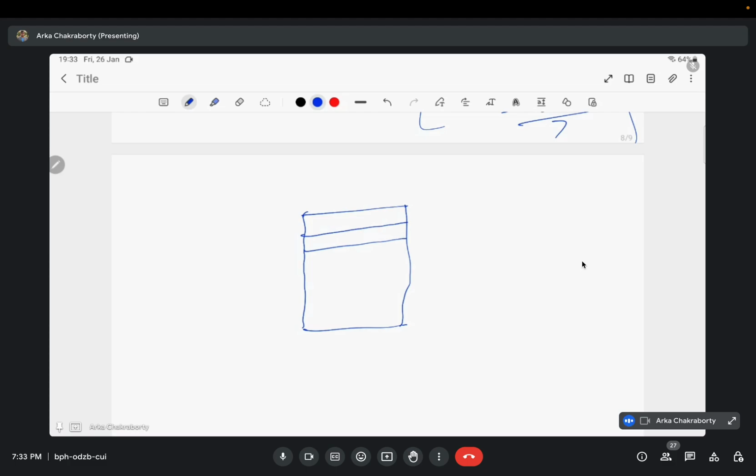Say it is a MOS capacitor. The upper layer is metal, the middle layer is oxide, and the bottom layer is semiconductor. So, metal oxide semiconductor. Say it is p-type silicon. This is called the gate terminal, and this is the body terminal which I have grounded. Let us see what happens when I apply different voltages at the gate. We will see it qualitatively, not quantitatively: not the equations or how much charge will be stored, but what is happening basically.